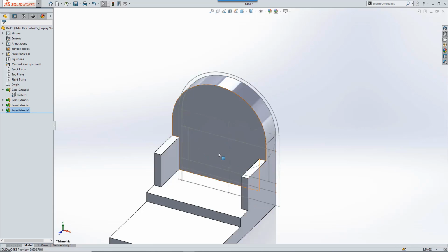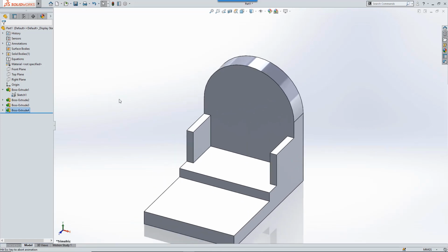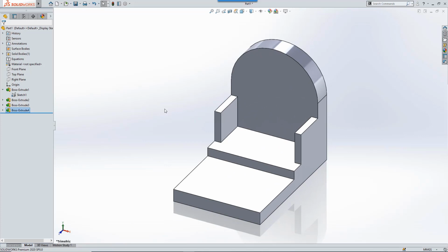Again here we'll fill in a value of 50, choose the two outer contours and right click for enter. Now you don't need to use the S key to start the Extrude tool. You can do it in a slightly different way. What I'm showing you here is mouse gestures, and I've added hide sketches onto my mouse gestures. So if I drag down, I can select hide sketches, as we don't need to see that sketch anymore.